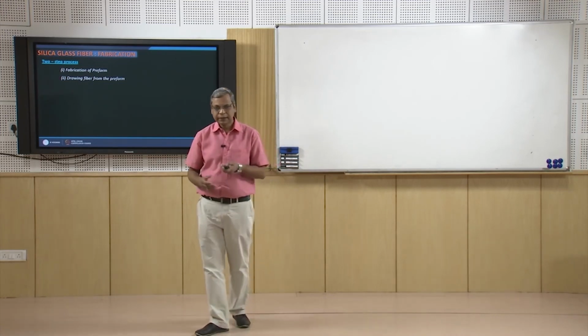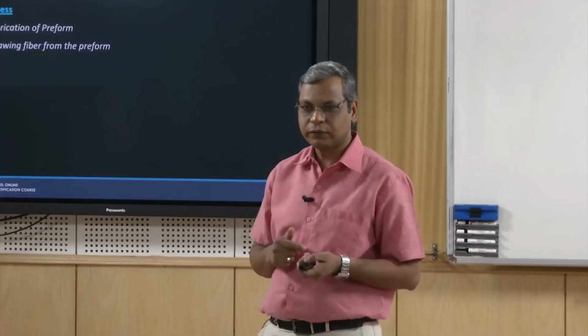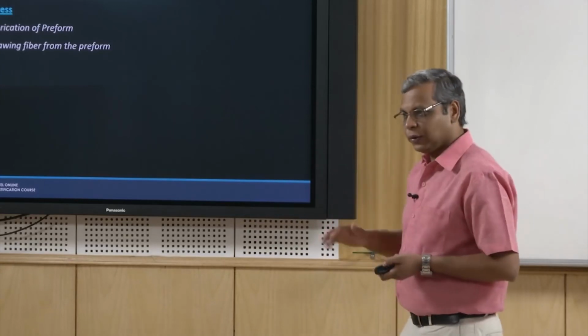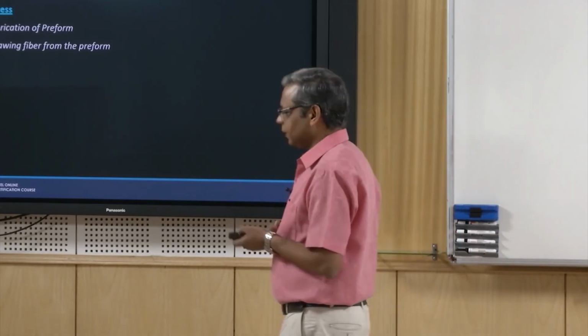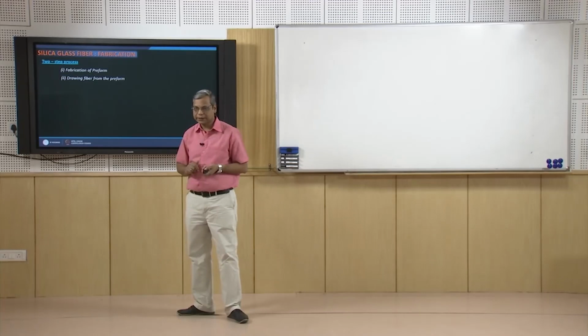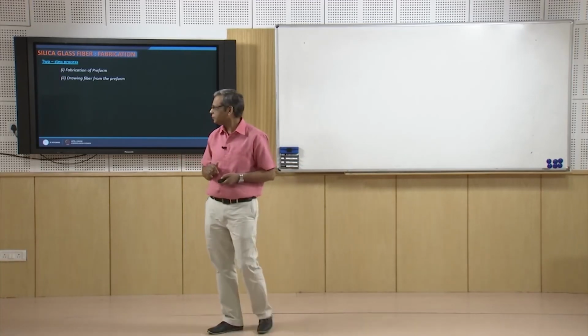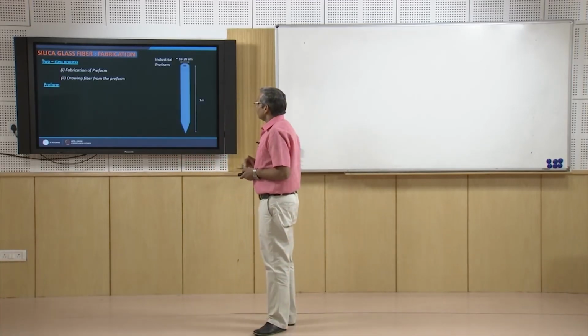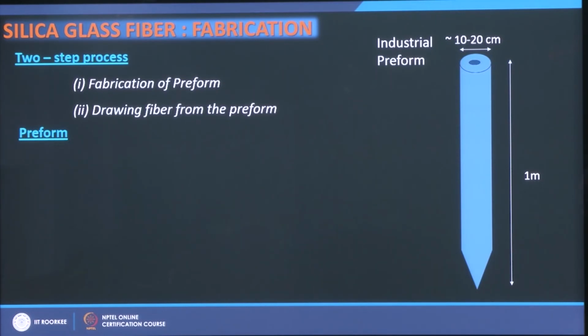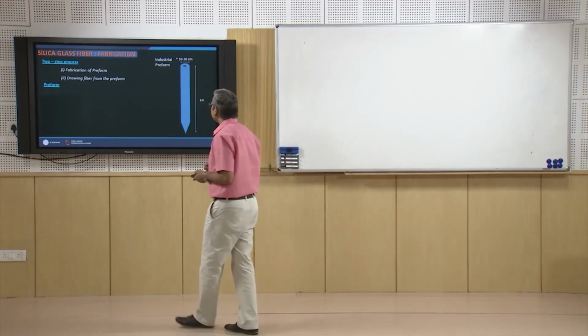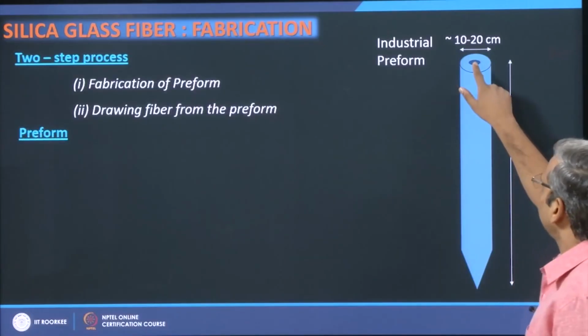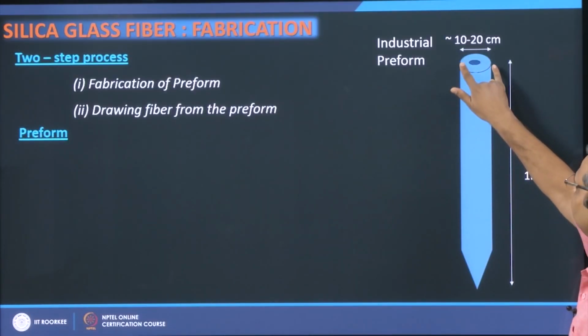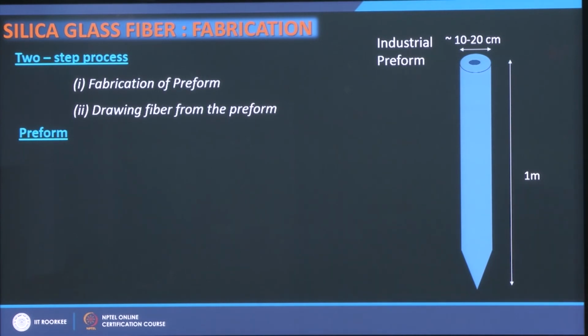However, this kind of fiber where you have pure silica core and fluorine doped cladding is used in an environment where there are nuclear or ionizing radiations, because there germanium does not work. Germanium develops some color centers and then optical radiation is absorbed by those color centers.